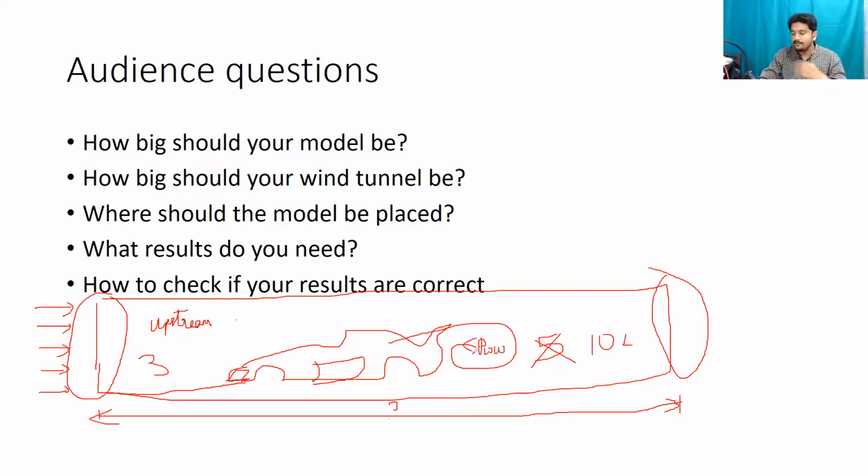So the idea is very simple. When pressure becomes low, usually the flow here is taking place only in this direction, correct? But when pressure becomes low in the wake region, flow comes like this. And then because of this, there is a vacuum. So basically flow is getting pulled into the vacuum and you start getting a recirculation region. And this recirculation region is also going to move, making the process very dynamic.